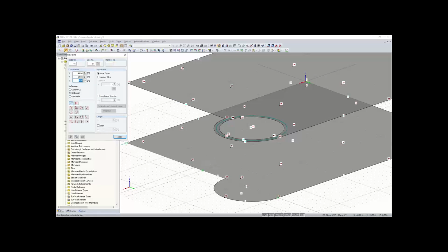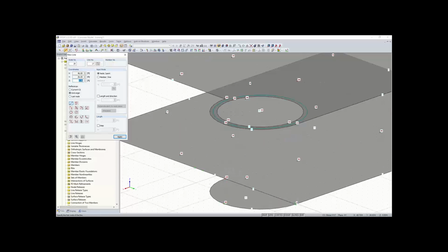And this is going to be about 7 feet away from node 20 here. So that will be at 4619. So we'll go to 4619. I'll draw up to the line, and again, you get that nice symbol there, that snap point for perpendicular, kind of like AutoCAD, and there you go.